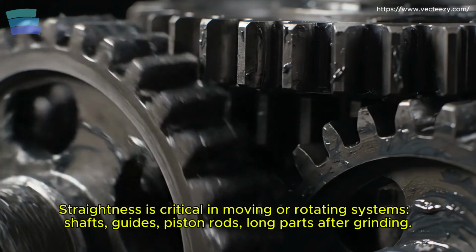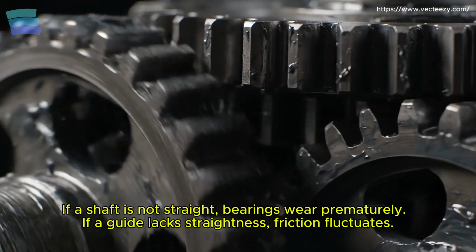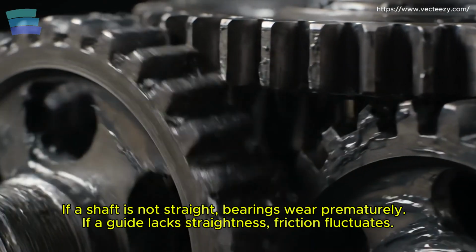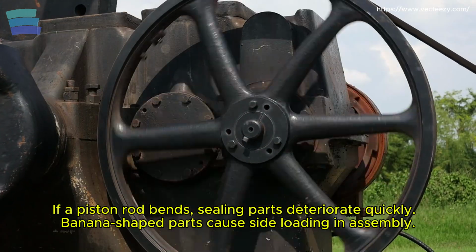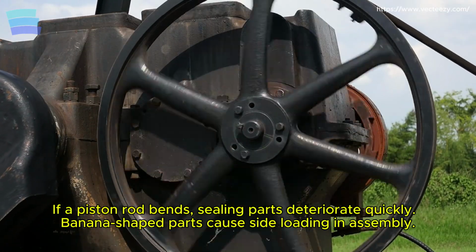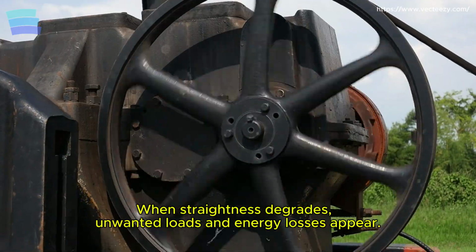Straightness plays a critical role especially in moving or rotating systems. If a shaft is not straight, bearings wear prematurely. If a linear guide lacks straightness, friction force fluctuates. If a hydraulic piston rod is bent, sealing components deteriorate quickly. If long parts come out of grinding with a slight banana shape, side loading appears during assembly. In short, when straightness degrades, the system experiences unwanted loads and energy losses.